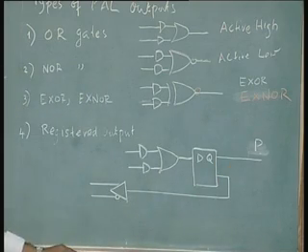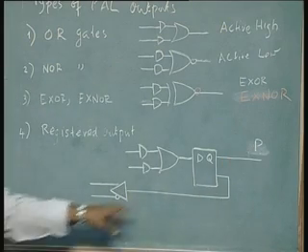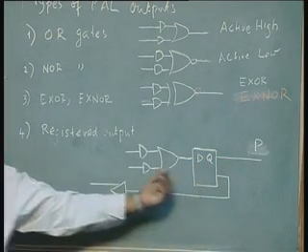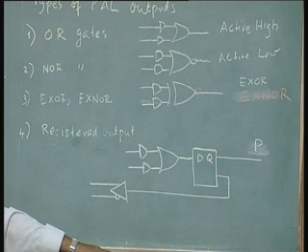One of the output variables is a p, it's a registered output variable. And suppose I want to use this p value in my design, that is what is done in a typical sequential logic design. In a sequential logic design, you have the combination logic and the previously stored values from flip flops, together they determine the next output.